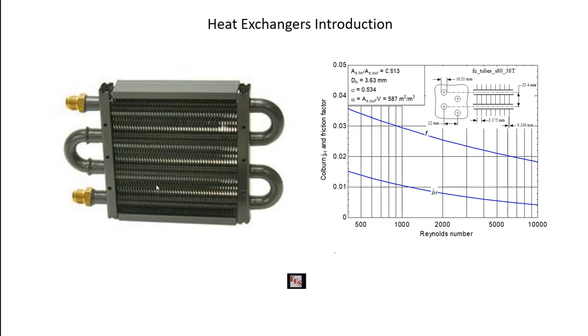So if you think about what's going on here, we have flow through these fins. These are plate fins that have some kind of corrugations to them, but then also flow over the tubes. So these are tubes inside of here that the flow has to go over. So this is some aspects of flow through a duct, some aspects of flow over a tube. Obviously it's a complicated situation. And the correlations for these compact heat exchangers traditionally have been obtained using what are called compact heat exchanger correlations.